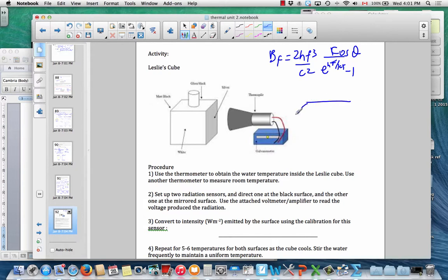So we said, okay, there's a hot surface here, and we want to integrate and find all of the radiation going in all of that half sphere over all the possible frequencies that this hot object could be emitting, and that took us to this new law, the Stefan-Boltzmann Law: sigma epsilon area, temperature of the object to the fourth minus environment temperature to the fourth. Now, there are going to be times when you'll want to use the Planck function, and times when you're interested instead in the total energy that's being emitted.